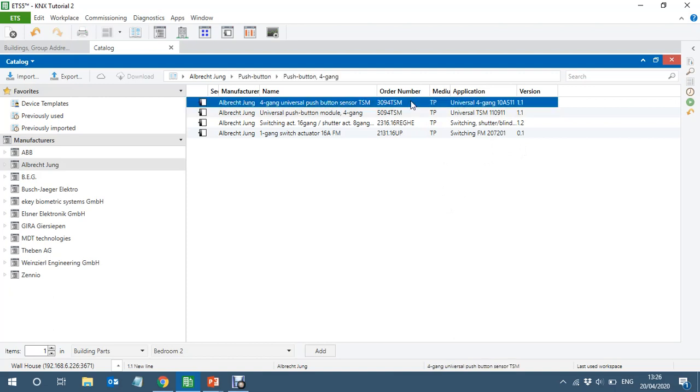So when I tried to download it, it was giving an error, just saying the database is not for the right device. So make sure you check the firmware version of the devices if you are getting such an error.